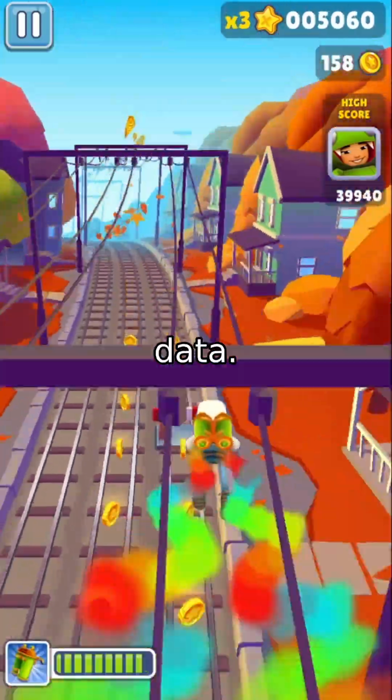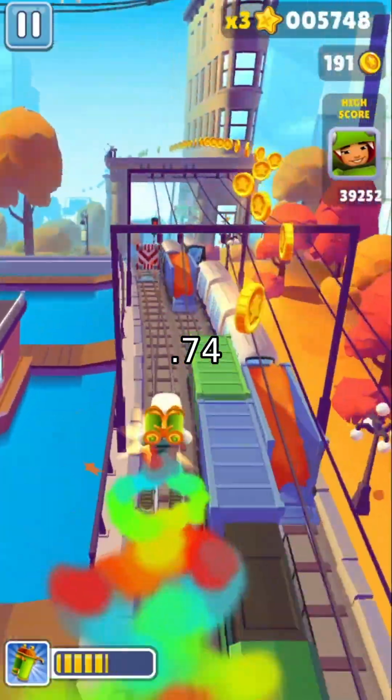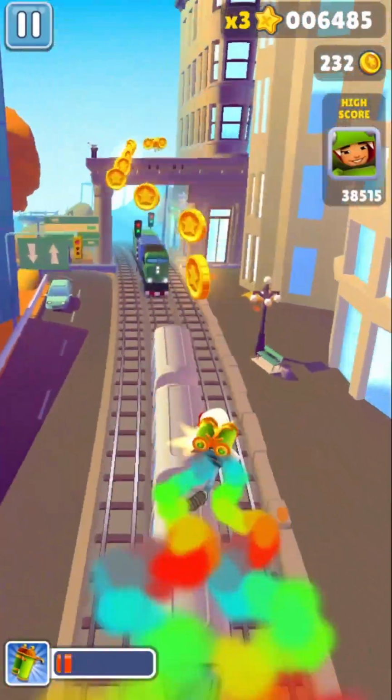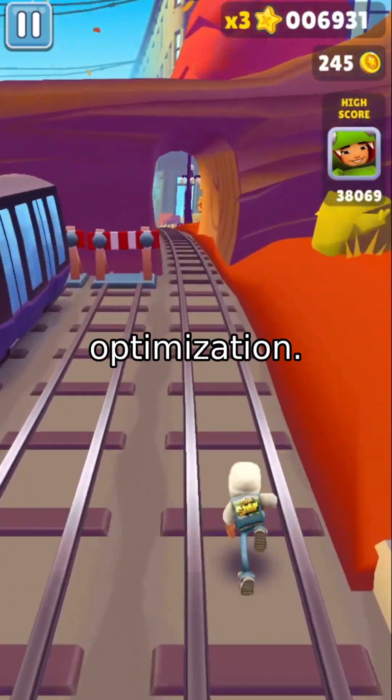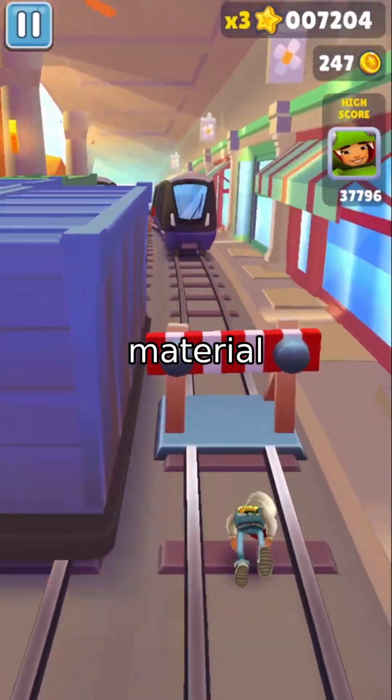never on benchmark-specific data. On the 64 times 64 benchmark, OAT achieves 1.74% compliance error, a 32% reduction over the previous state-of-the-art. Even without any post-processing, it outperforms models that use 10 steps of direct optimization. Volume fraction error is just 0.25%, showing precise material usage.